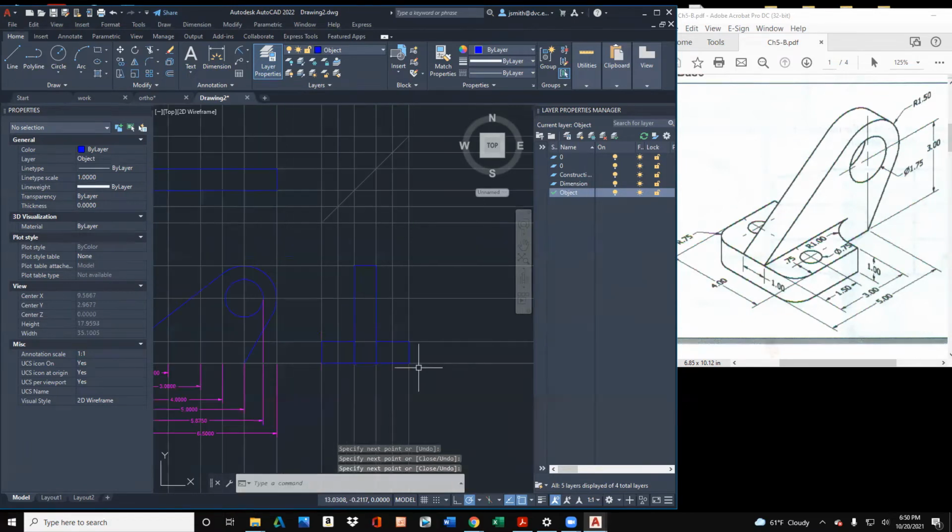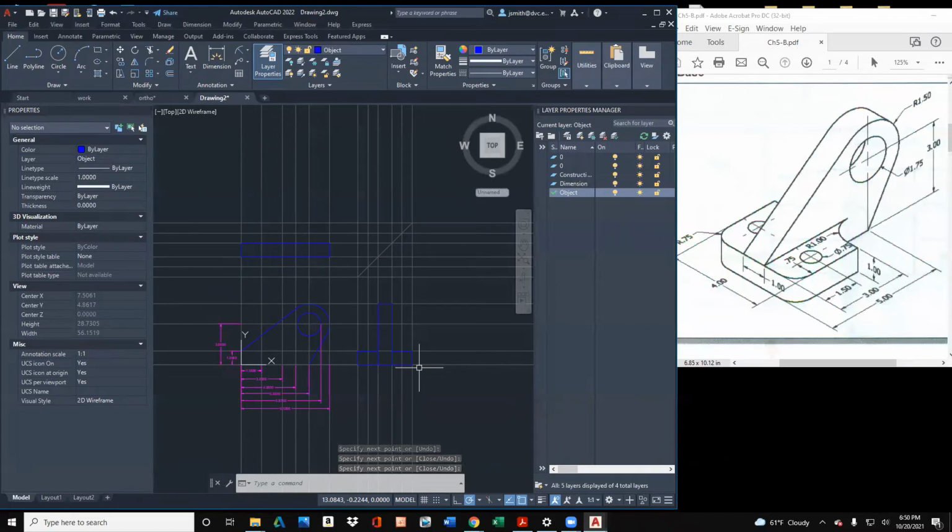And so then what you would do is, if you were going to draw your hidden lines, that's the center line. So let's go ahead and draw that circle here. So from the top view, I'm going to just go back to the object. I'm going to just give it what it's telling me. It says that's 1.5 inches over. So it's going to be right here. And I'll type in the radius is 0.7 or the diameter 0.75. That one right? No, that's radius. Let's do that again. So the diameter, circle, diameter, 0.75. Enter.